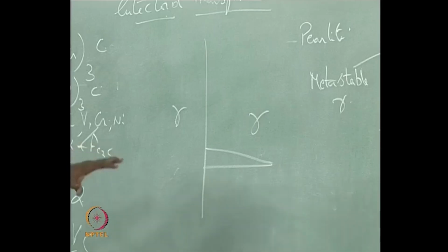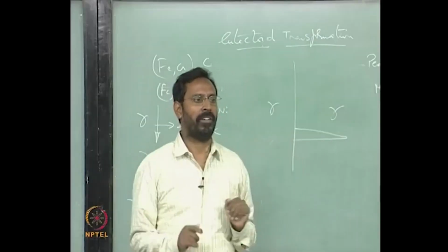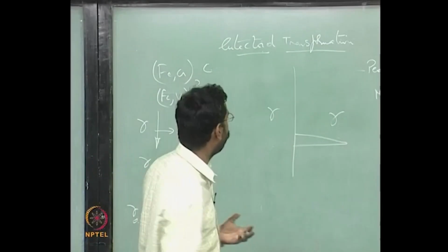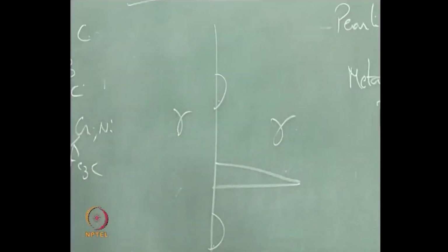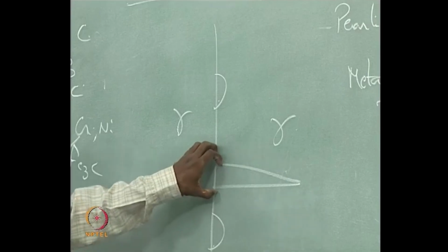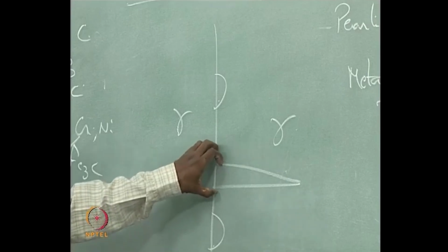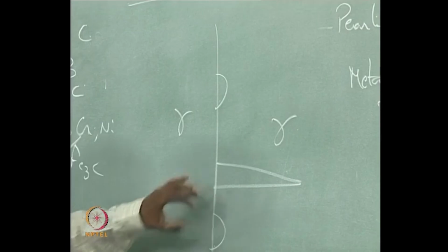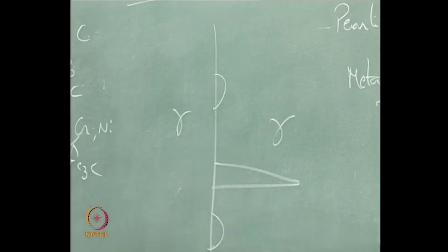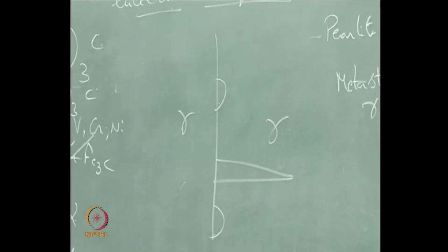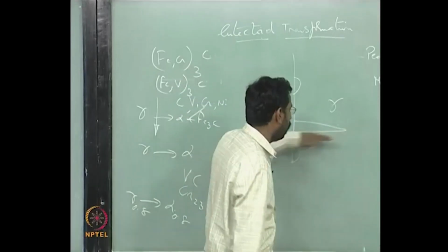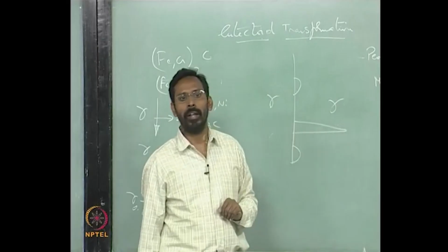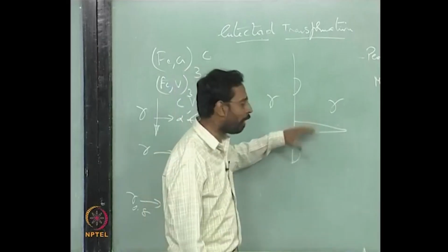So you see that precipitation forms like platelets rather than forming at a grain boundary as what is called grain boundary allotriomorphs. This is what people call the Widmanstatten structure. Widmanstatten structures come at low temperature, because at low temperature, in order to have the strain compatibility or the interfacial energy compatibility, you would see that it would form on specific planes, so that you can have a coherency.